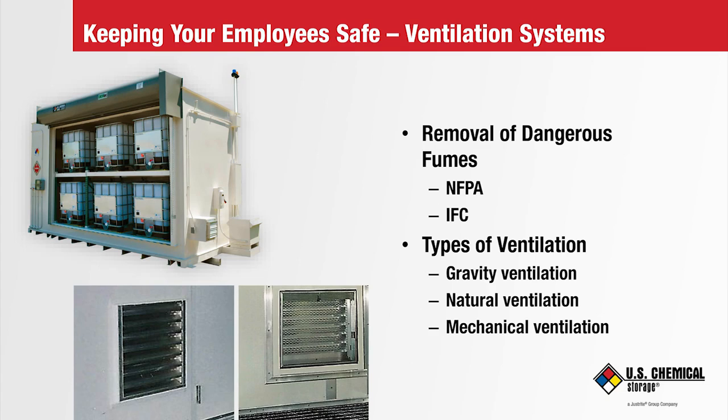Now, when a chemical storage building is installed inside a larger building, the fan must be installed on the roof or wall of the user's building. Negative pressure must be maintained all the way from the chemical storage building through the duct to the fan. If the threat of an explosion is high, and or to avoid installing explosion relief, it is permitted by meeting the requirements of NFPA 69, paragraph 3.3.3, quote, ventilation or air dilution, end quote.